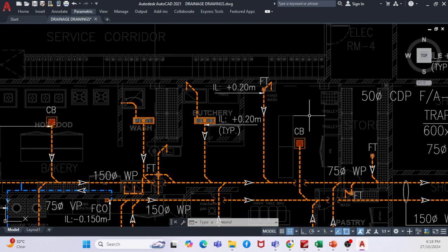Tell me. I will go with the same question of FD. Suppose now our drainage fixture value according to the IPC table is 2 DFU. If we consider 5 floor drains, then the size will be 20, which means we can move to 110 size from 75, because we achieved 20.